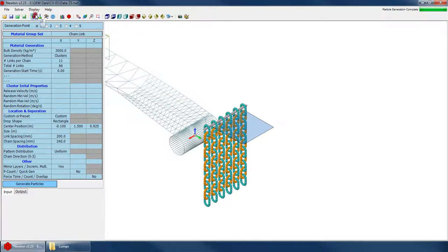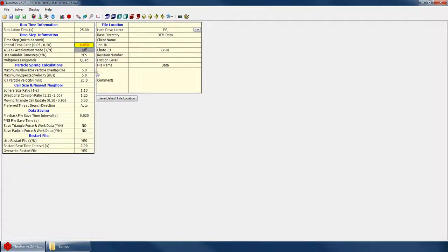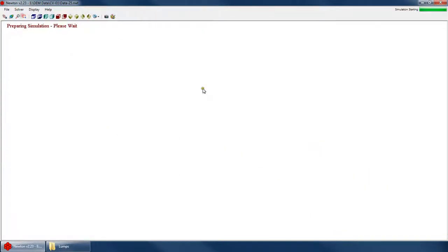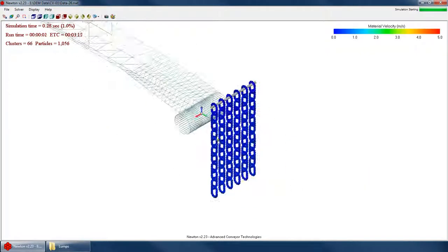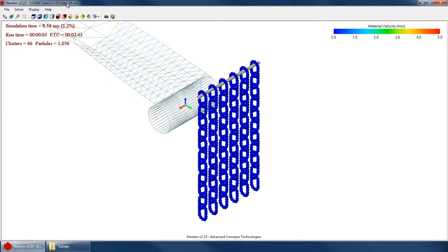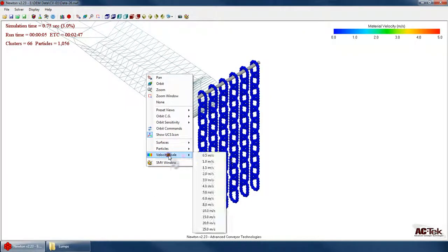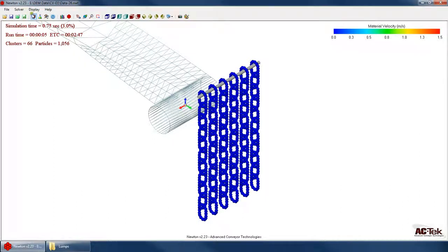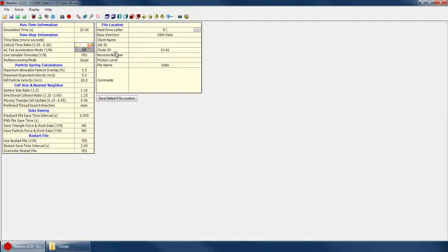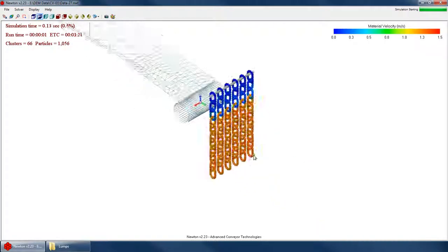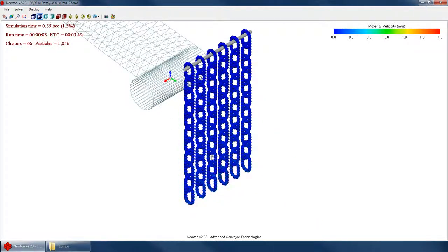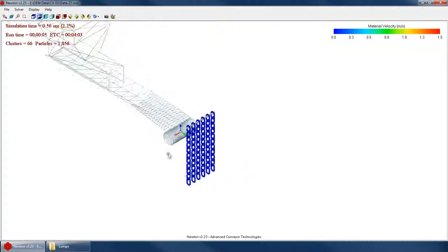And now if I go ahead and turn down my speed a little bit, and say solver run, you can see as we start the simulation, those particles kind of drop into place. Let's turn our velocity scale down to 1.5, slow this down some more, and try that one more time. Boom, boom, boom, boom, boom. Chains drop into place.